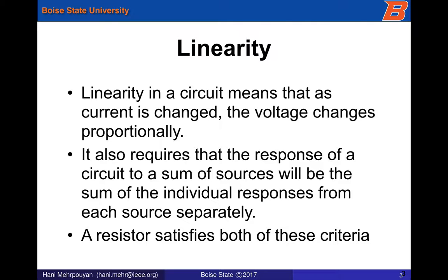So what does linearity mean? Linearity in a circuit means that when a current is changed, the voltages will also change proportionally with respect to those currents. What it also means is that if you have a certain number of sources of power, then the overall circuit response is equivalent to the sum of the responses from those individual power sources.